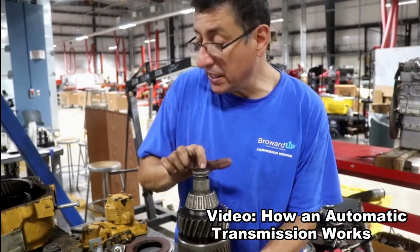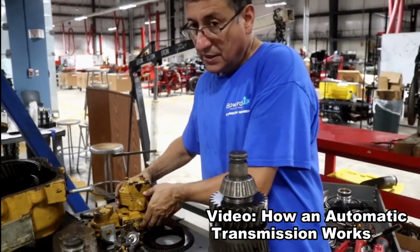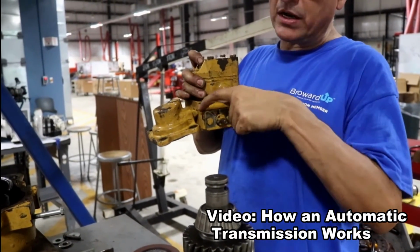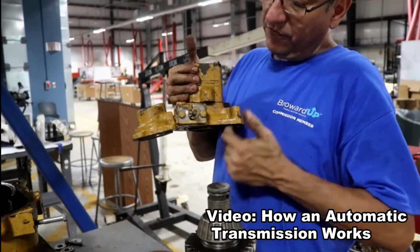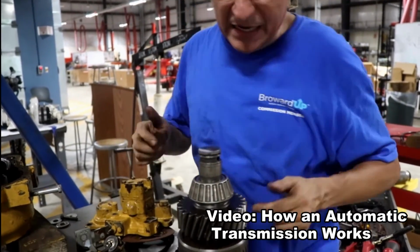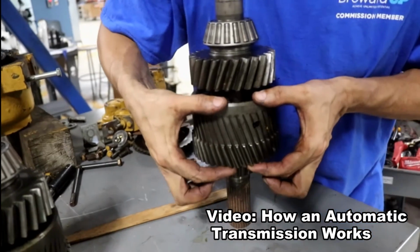When the fluid enters here, because this one is selected in forward, the valve body sends the fluid here, passes over there, and immediately enters the clutch pack.